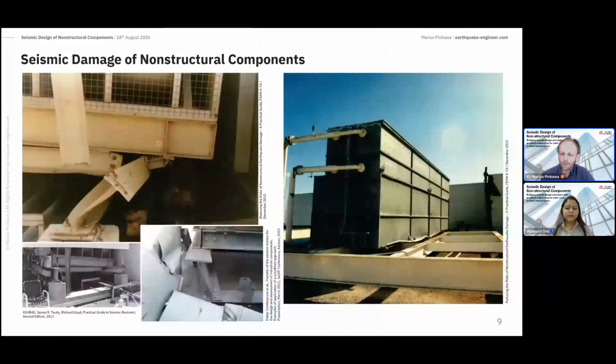And we also need to design the component itself, because here you see some stability failure, and here you see damage to the supporting structure. So probably this beam is also loaded in its weak direction. It was not designed for this lateral seismic force. So it is often neglected, and this is why we often observe seismic damage to non-structural components.